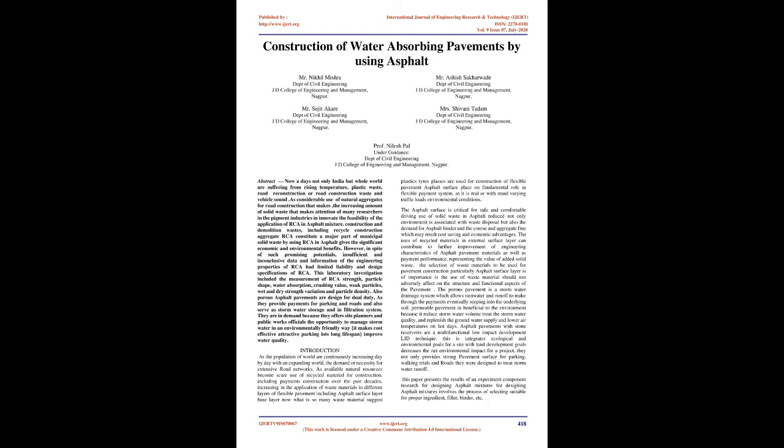However, in spite of such promising potential, insufficient and inconclusive data and information on the engineering properties of RCA have limited its use and the design specifications of RCA. This laboratory investigation included the measurement of RCA strength, particle shape, water absorption, crushing value, weak particles, wet and dry strength variation, and particle density.